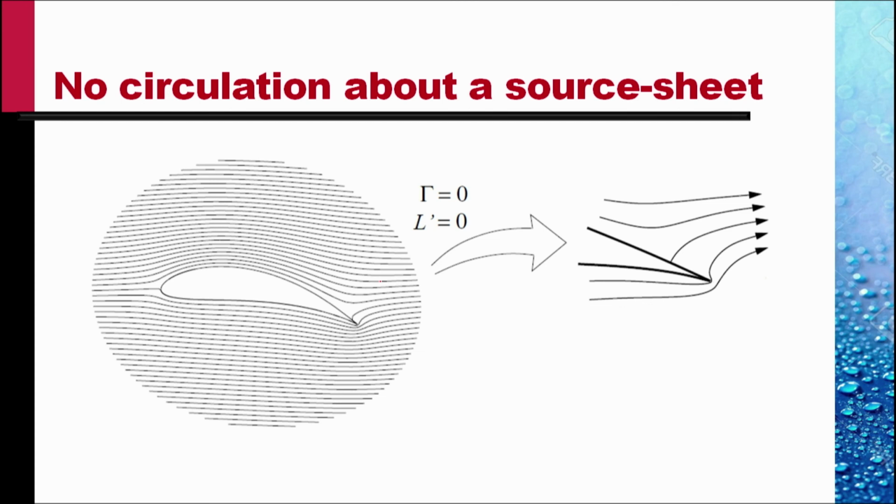As we have seen, the trailing edge is this. The flow goes around the trailing edge, acquiring an infinite velocity at the rear point. The stagnation point moves up. So there is flow which is slowing down in this region and in this region. This results in separation.